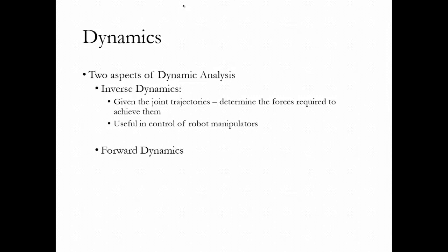And then the other aspect is forward dynamics, which is actually more concerned with the simulation of robots. So this is also a growing, contemporary field, where we assume some forces are acting, or the torque profile is acting at the joints. How would the robot actually behave? What will be its joint trajectories? We can basically simulate them beforehand, without even constructing these robots.